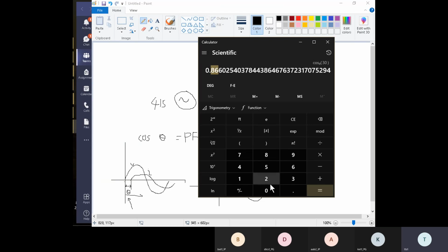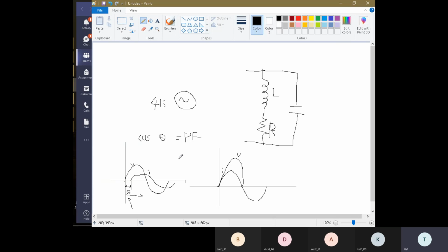If the power factor goes to 0.5 or less, or anything close to 0.5, it's going to be a very serious issue for TNB, the company that supplies the electricity, because they're going to supply more power to fulfill your needs. But your energy meter is based on the kilowatt.